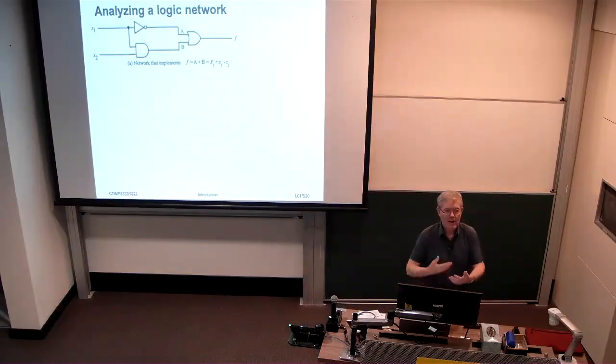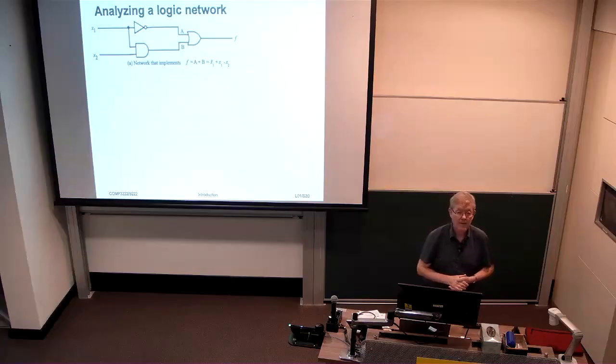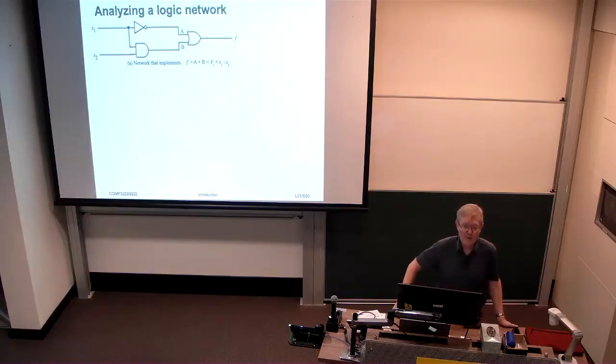How do we know how that behaves? When you write not x1 plus x1 x2, how do we know whether the AND or the OR is first in the order of operation? That's a good question. When it's drawn like that, the AND binds more tightly, and the NOT binds even more tightly than that. But we'll see in a moment, the VHDL doesn't care, and you have to use parentheses. All right? Okay.